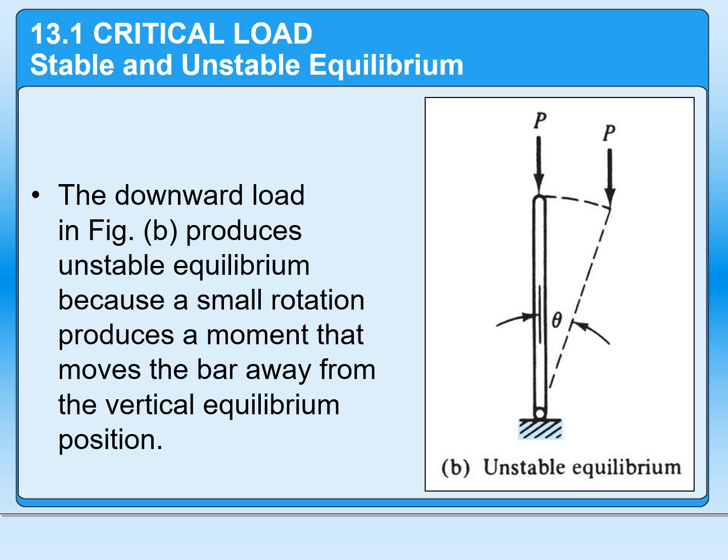On the other hand, configuration B is considered unstable equilibrium because in its initial position, the overall structure is in equilibrium. The fact is this downward force is being counteracted and it will remain stable if nothing changes. But keep in mind, it has to remain perfectly vertical. Any small changes to the left or right is going to cause a small rotation, which is actually going to magnify the effect and actually cause a greater rotation. As a result, there's no self-correction here at all. If anything, the instability is going to reinforce itself.